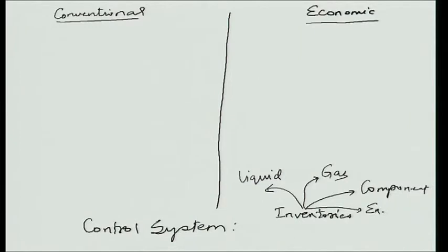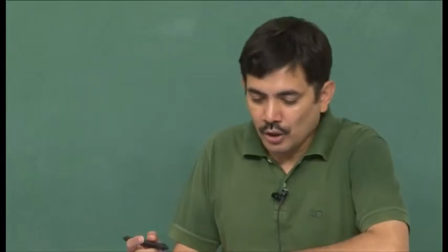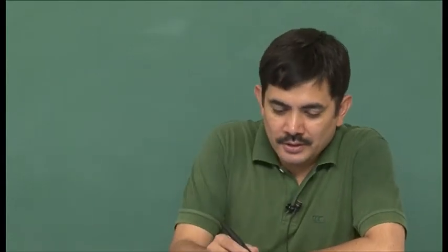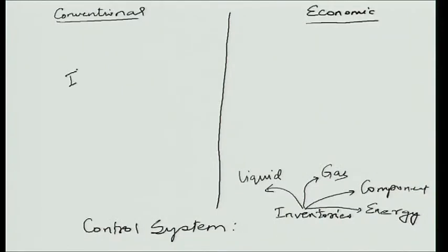You see, what does the cooler, what does the reaction heat removal mechanism on a reactor do? It basically removes the energy released by reaction. Now, it is the job of the control system to ensure, you must have seen this equation so many times, accumulation of whatever, of material, of component, of energy is equal to in minus out plus generation.